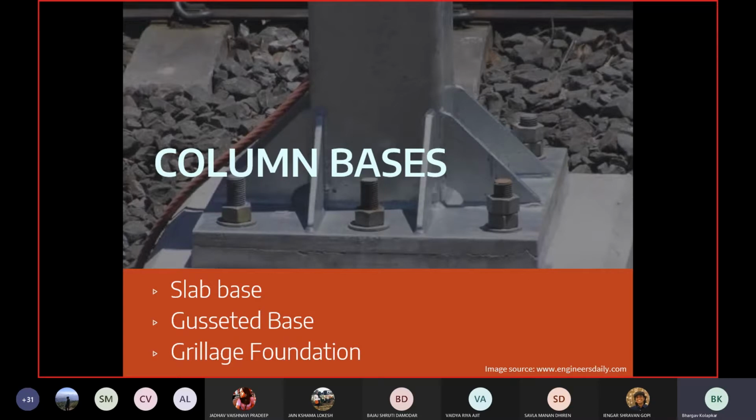Can anyone guess what the reason can be? Is it because of water? So we will have to treat it a lot. And why is that? Steel corrodes, so its structural strength would reduce. Exactly. So the most important concern here is that the ground is going to have soil. Soil is going to have water, salts, minerals. So it is a perfect recipe for corroding steel. If you place steel in the footing without really covering it, or without treating it extensively, there's quite a good chance that your section might corrode, and you cannot see it.